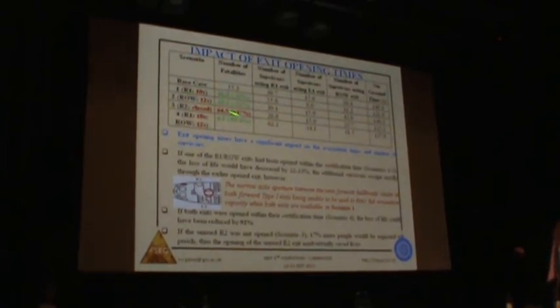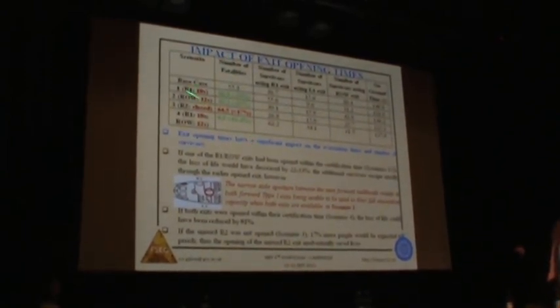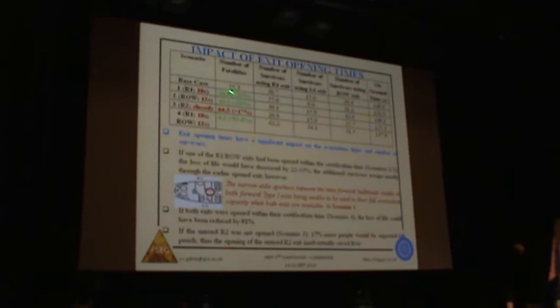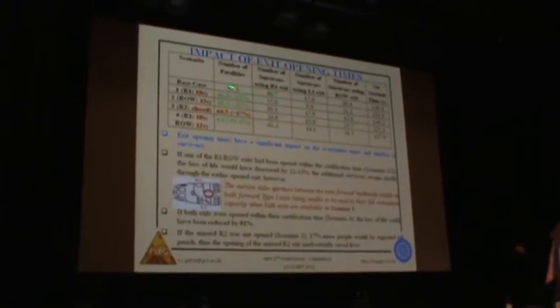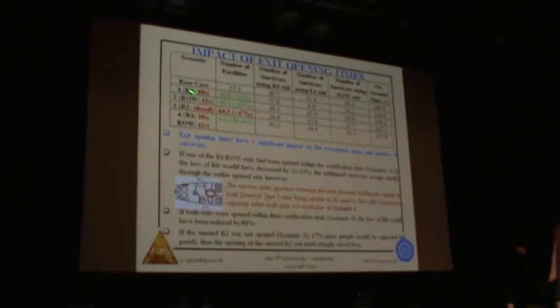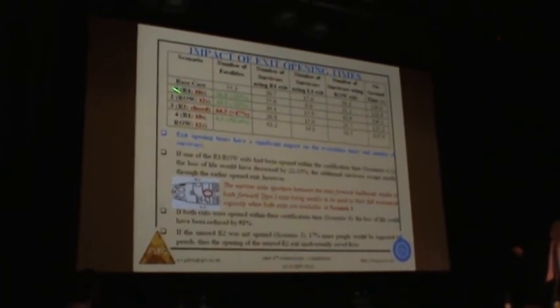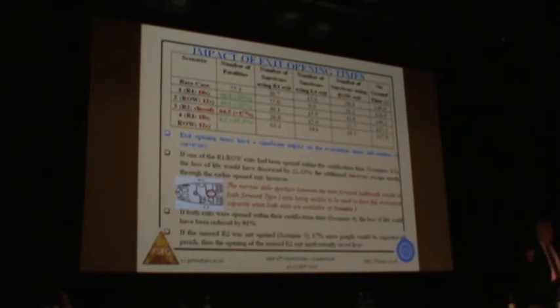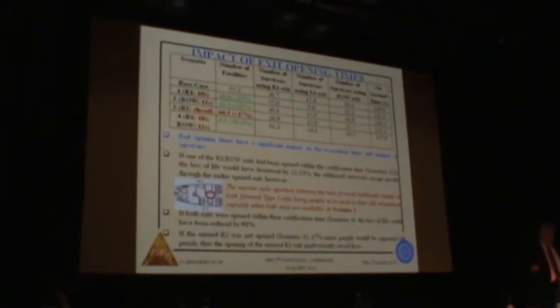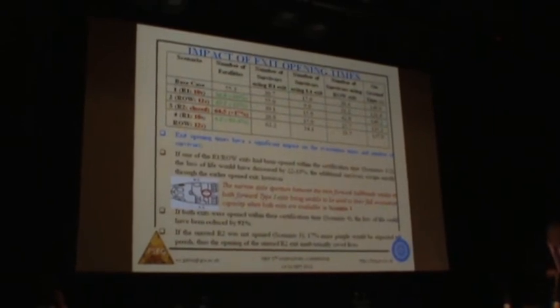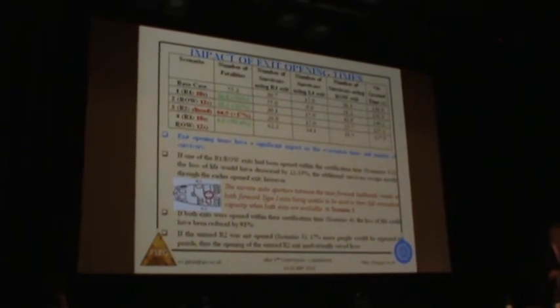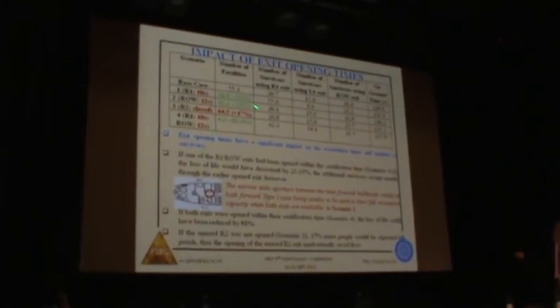Now these are the interesting results. These are the number of fatalities for the different scenarios. In the base case, we predict 55.3 fatalities. In reality, there was 55. When we opened the R1 exit 10 seconds earlier, the number of fatalities dropped by 33%. So if the guys on board the aircraft could have got that right overwing exit open on time, you would have saved 37 lives, just simply by getting that exit open quicker. The fatality rate would have dropped by 33%.